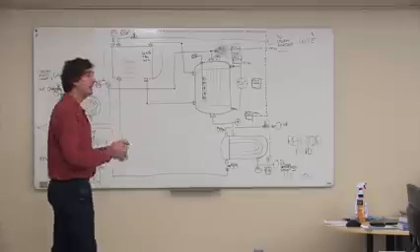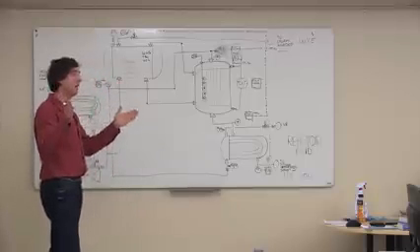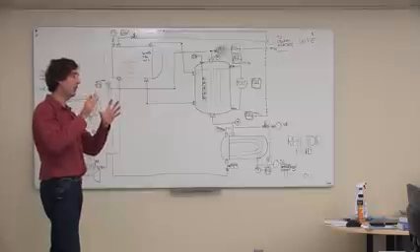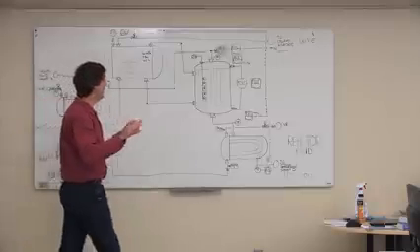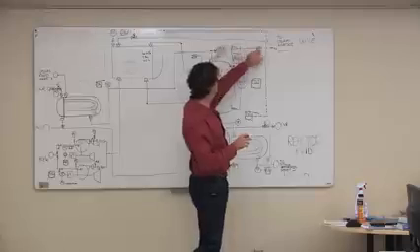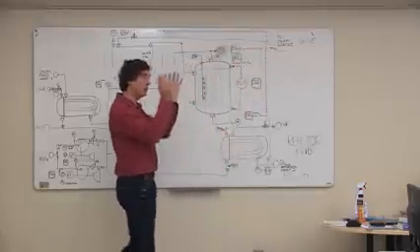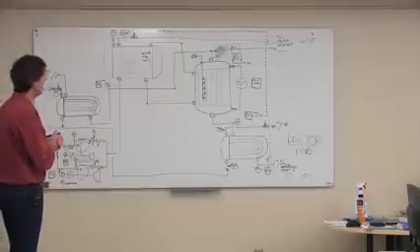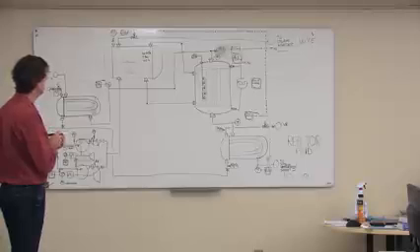So you'll probably have to take that P&ID that we did for the PHA, and a bunch of you noticed that the speed indicating controller on that compressor goes off the page like this, and it goes somewhere else, so you need to hook the controls up for that. Okay, so that's the process side.